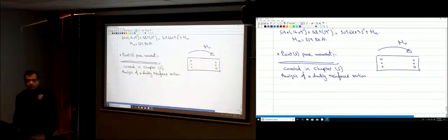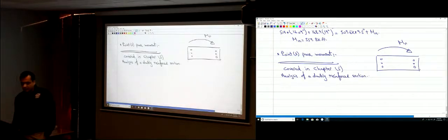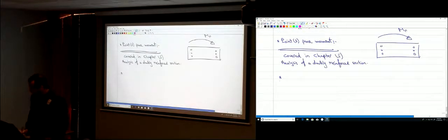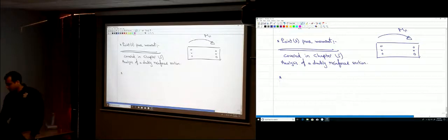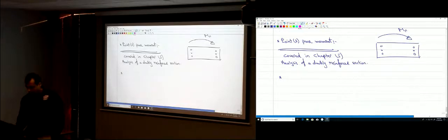So how do you proceed for an analysis of a section? First, you assume that the steel yielded or didn't yield. So here I'm going to assume that the steel didn't yield, although we usually start by the assumption that the steel yielded, but to save time here, I know it's not going to yield.